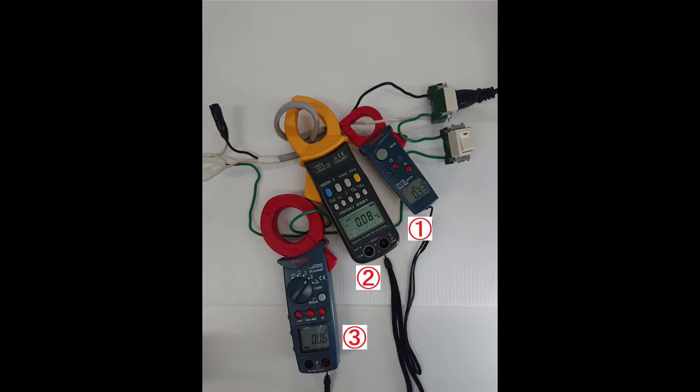In an actual on-site investigation of the leakage location, we measure all the wiring connected to the load, such as clamp 2, and check the measured value. In a circuit with current leakage, the current value is measured as shown in the photo. If there is no leakage, the current value is 0. The above is an explanation using actual photos. I will explain this with a video of actually turning the circuit switch on and off.